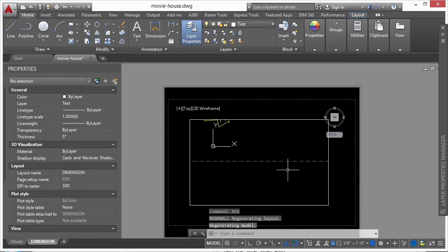Sometimes they get really big. If I refresh my screen, they'll reset, and they'll set so that these dashes are at the proper length for when you print them out. So your dashes, regardless of the scale of your drawing, will come out the same length. I could have a viewport that's a 1 to 40 scale and another one that's a 1 to 200 scale. Two very different scales, but the dashes will come out the same length and size. So that's good. That's what you want.